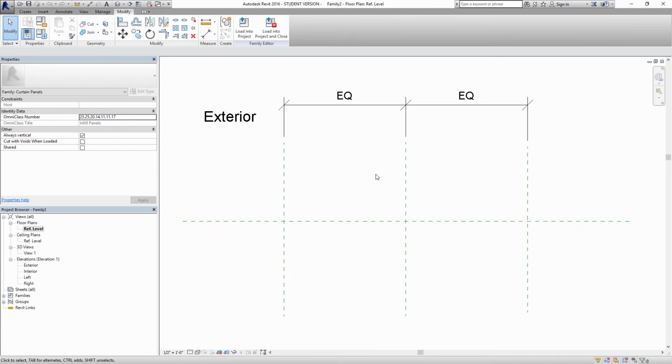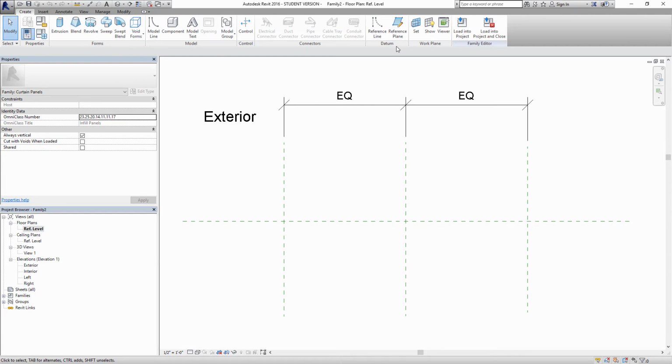Let's imagine that we want to have a panel that sticks out, and we want to be able to control the depth of how far it sticks out and create a series of different panels that maybe are a 6-inch pop out, 8-inch, 12-inch, 400-inch, it wouldn't really matter. We're going to start off initially by doing just a simple extrusion, and then we're going to change and do a panel that tapers.